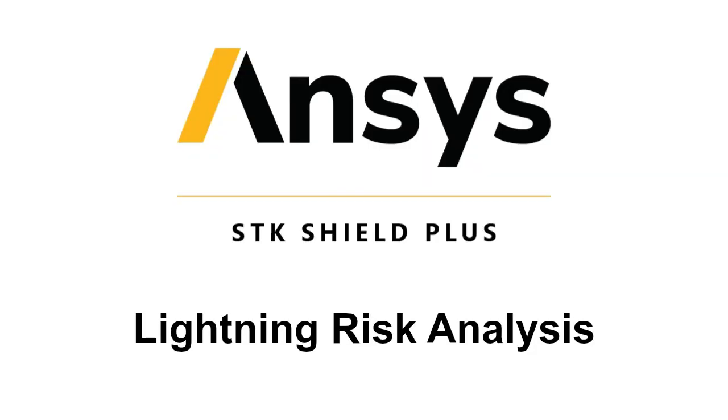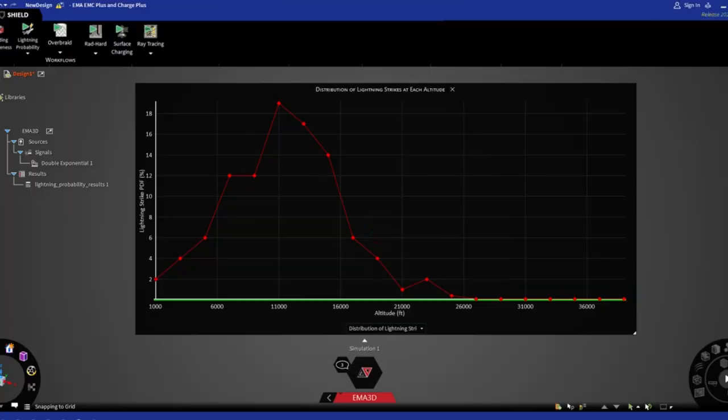For our third workflow in Ansys STK Shield Plus, we have the ability to assess the probability and consequences of lightning strikes on an aircraft path that you would have modeled in Ansys STK. The results provide a probability distribution as well as a typical waveform for the lightning strike current that is associated to the exposure that the mission would have.